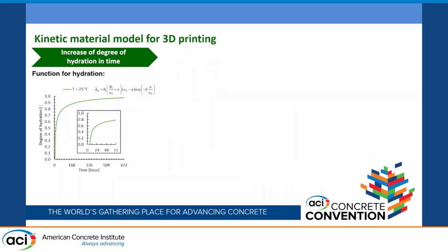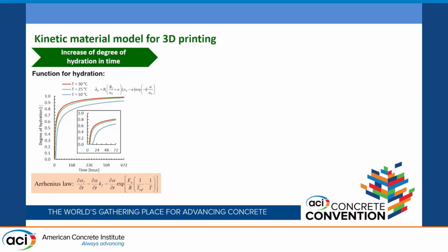And how do we address the evolution of these material properties? Of course, we can define time-dependent functions for each material parameter, like the tensile strength and fracture energy, all of them, but usually you don't have those. They are not available. If you can measure tensile strength development or compressive strength development in time, that's the best way, but usually you don't have that.